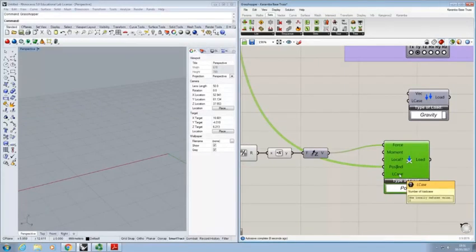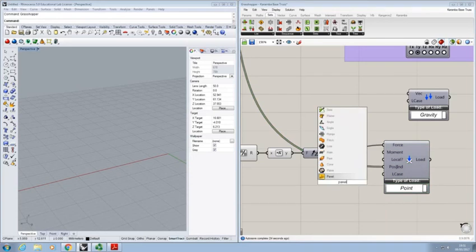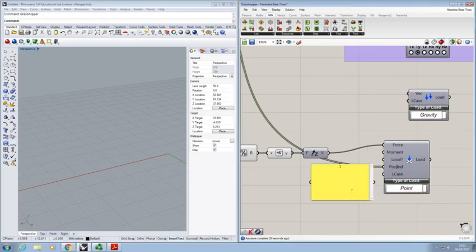And for the load case, we would have to change this because at the moment we have 2 load cases which are 0, which is fine, but it means that when it comes to reading the results, we won't be able to know how much of the deflection or internal forces come from gravity, and how much come from this live load that we've applied separately. So all we need here is a panel with a value of 1. And now this is load case 1.